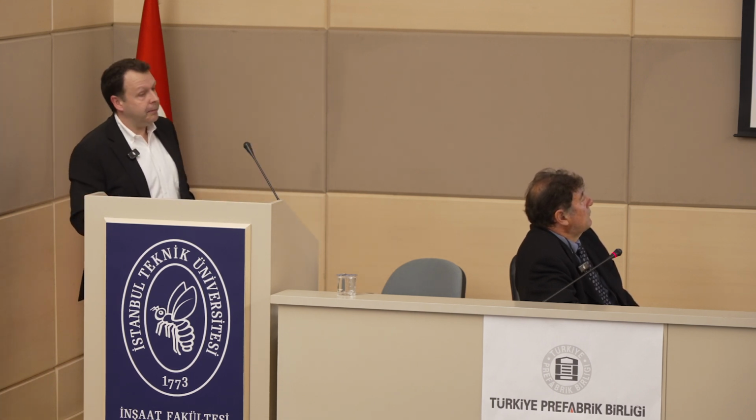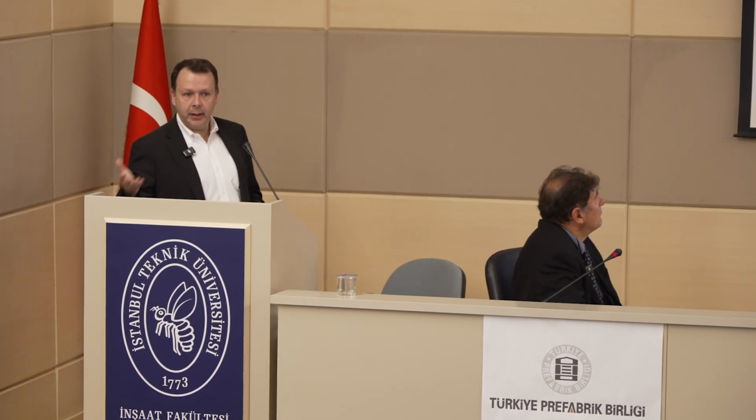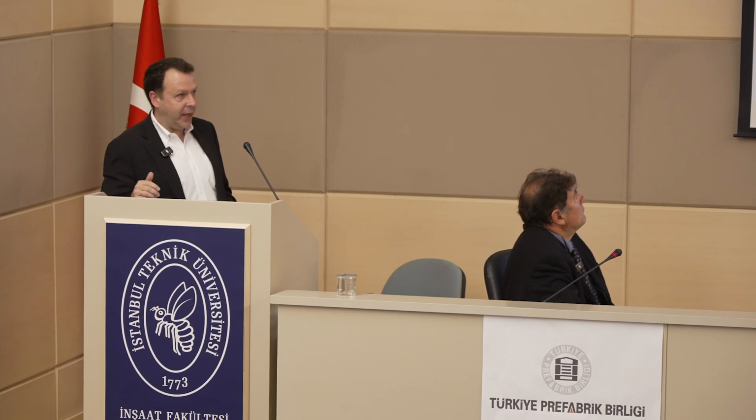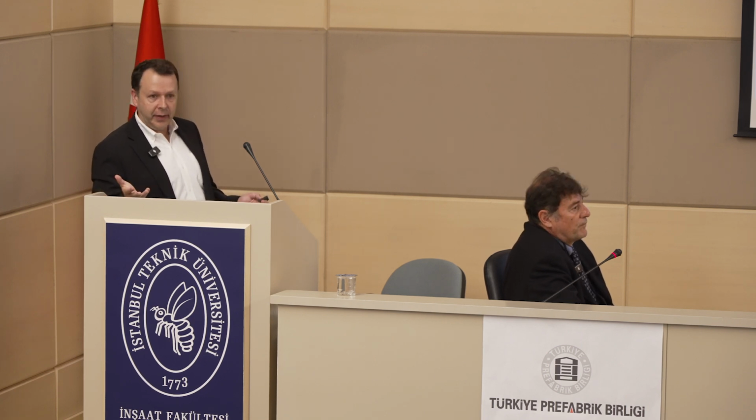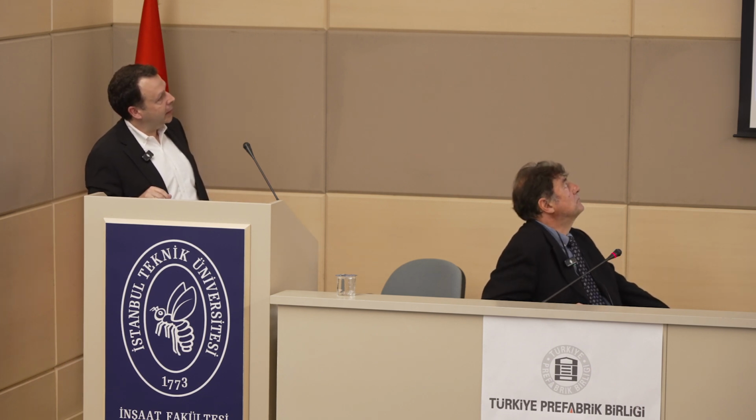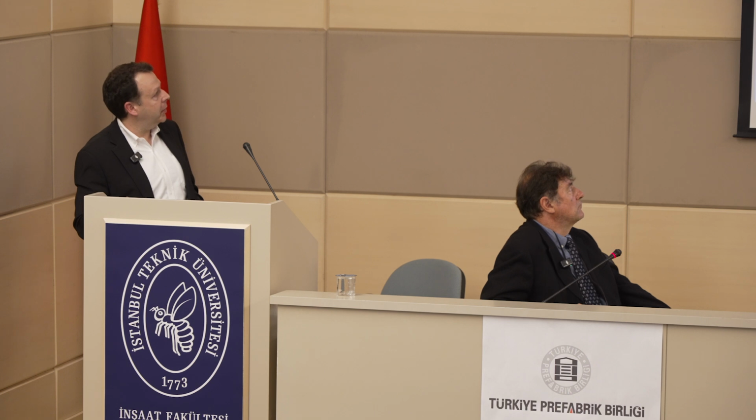So per ACI, and I think from what I was noticing is what you do here as well, you use the effective stiffness, 0.7 Ig for columns and 0.35 Ig for beams. And then we modeled the hinges and did moment curvature analysis for the beams to develop our moment rotation backbone for the beam hinges.